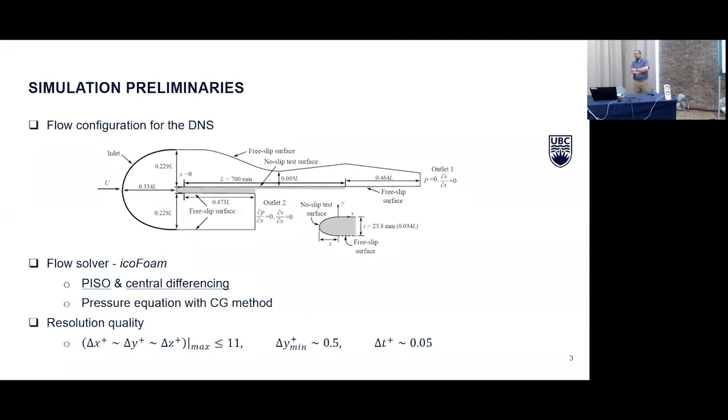We did look at them, but they're not nearly as easy to interpret in the context of the turbulence because it's a scalar quantity. And so it's hard for us to understand the interaction between the wall normal velocity fluctuations, the longitudinal velocity fluctuations, the shear stresses that are occurring there, and then the pressure term.